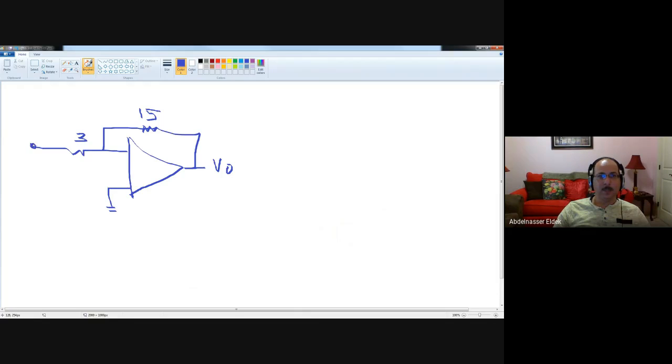Let's call the input just VI. What is VO? VO will be negative 15 divided by 3 times VI, which is negative 5 times VI.